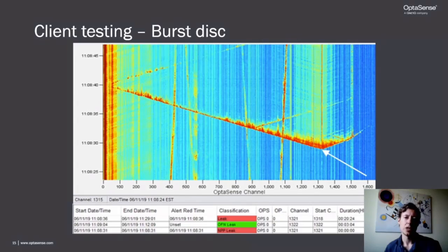In the image, the white arrow indicates the origin of the leak, with a strong signal propagating for many kilometers along the pipeline. A negative pressure pulse is time-stamped around 2 seconds after the event, and shortly afterwards the system detected orifice noise, which fused with the earlier detection.